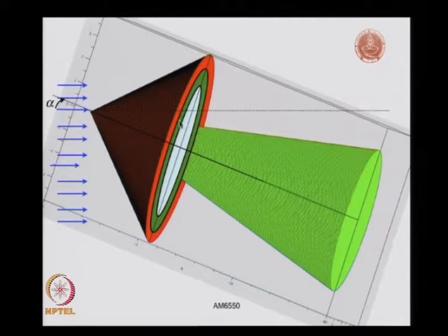Now, it is important to look here and find the difference between this and what we just saw, which is the axisymmetric case. Now my axis system would be to the free stream with a certain angle of attack. The lines of symmetry of the shock and the physical cone fail to coincide.